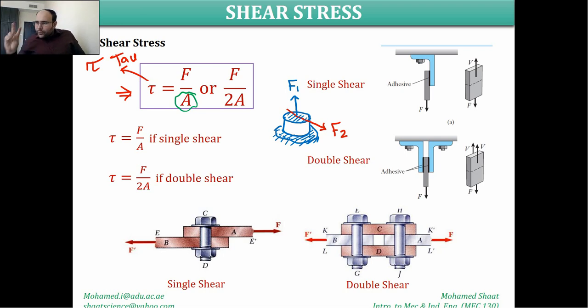So these are two forces acting over the same area. Yes, two forces acting over the same area. The area is just the cross-sectional area. Calculate the circular area of this circular cross-section of this pillar or this bar. Make sense? So the question is, this F1 will produce a stress.